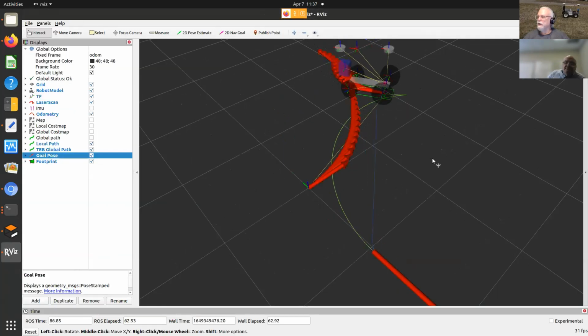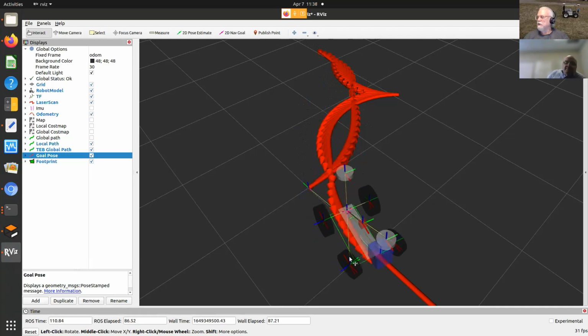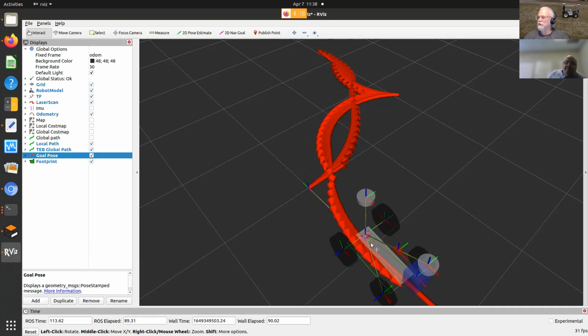And you'll see it won't do a lot of hunting. Once it gets down here, see it says go on this path, and my vehicle is set right now to turn sharp enough to actually follow that path. And you can control that in the tab planner. There's several things. Number one, you've got the wheelbase, which has to match your vehicle. And there's one that says like minimum turning radius. And there's a couple of parameters that you can change, because as I say, the tab planner says, I want you to drive on that path and expect your vehicle to follow that. And see, it came down and bam, stopped without doing any correcting or anything. So that's a good sign that it can do that. So theoretically, if I play with the numbers on Al's vehicle, I should be able to get his to do that.